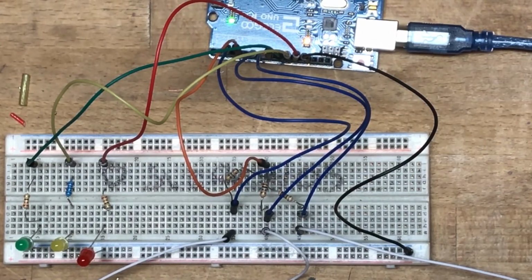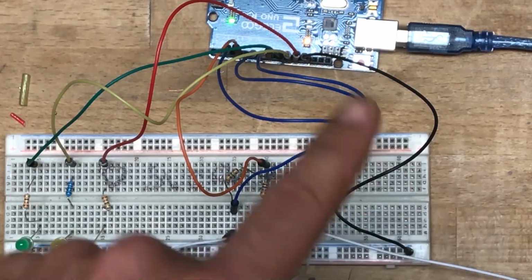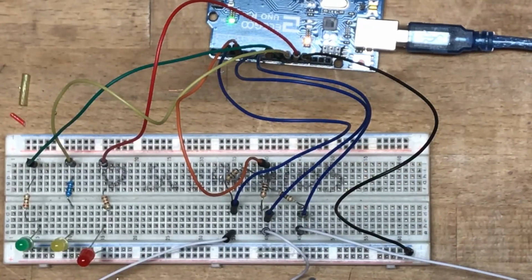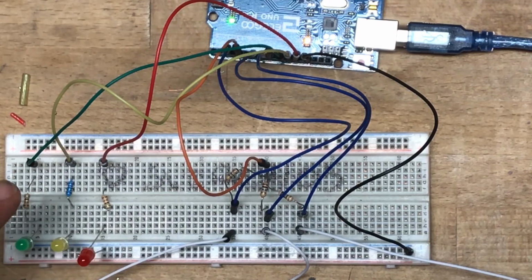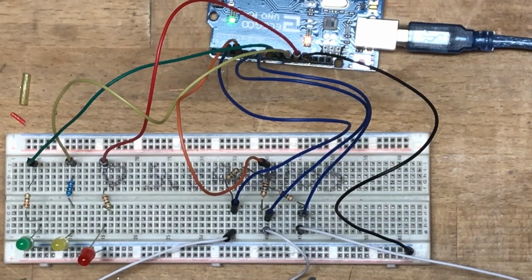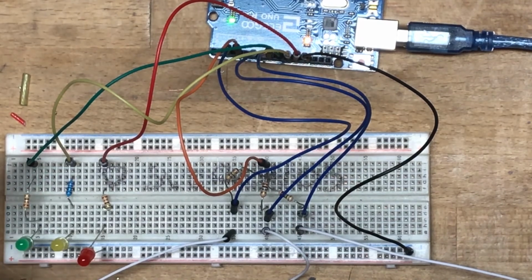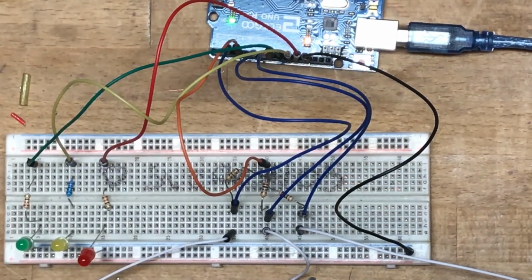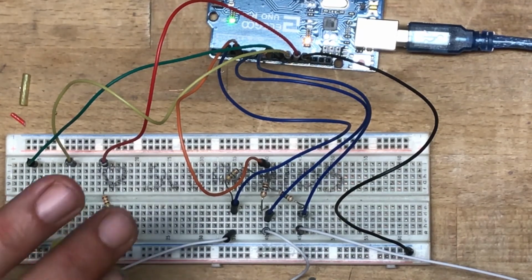So here's our circuit setup. We've got our 3 LEDs on the bottom left of the board, the short leg, the negative side going back to the negative rail of the board, and that's connected with this black jumper back to any ground on the board. There's close-up photos of all this in the class drive for this particular lesson if you need a little bit closer of a look. Each one of these LEDs is running through a 220 ohm resistor back to the board. I've got the wires color-coded per LED, and those are going back to 10, 11, and 12 respectively, green, yellow, red. That's one part of the circuit.